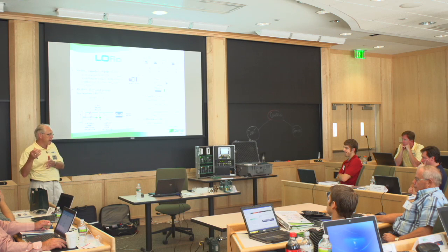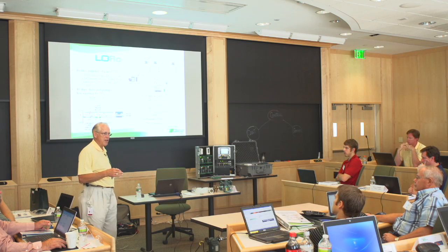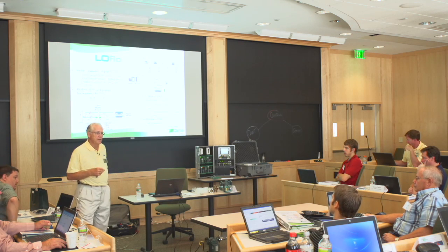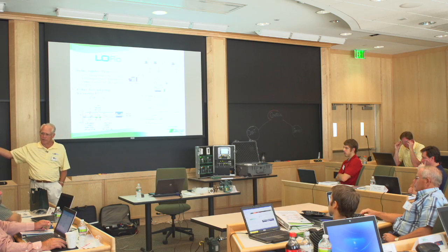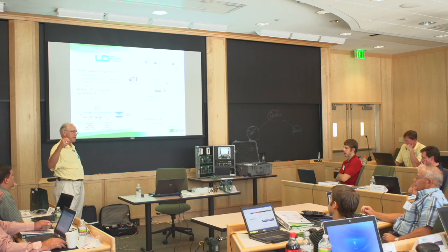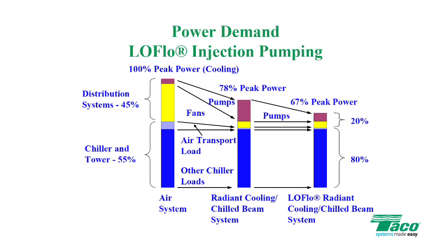Now, you would have had to do that anyway, because those would have just been diffusers. So the air side balancing cost doesn't change, but the wet side does. So by piping those guys reverse return, using the load match system already, then hydronically the system is still self-balancing and we're not increasing the balancing costs.